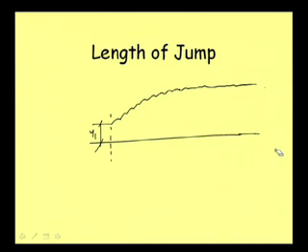Okay. Now, for that situation, we should see where the flow is becoming almost horizontal, then we can say the jump is ending. And when the jump is ending, we should try to see very precisely where it is ending. That point we should refer to as the end of the jump, and of course the depth there is y2.